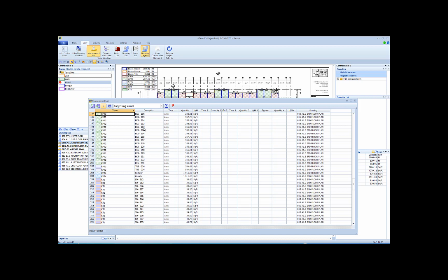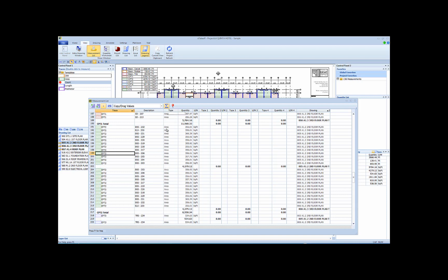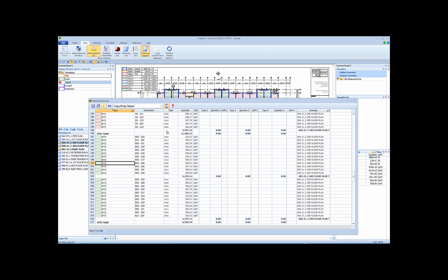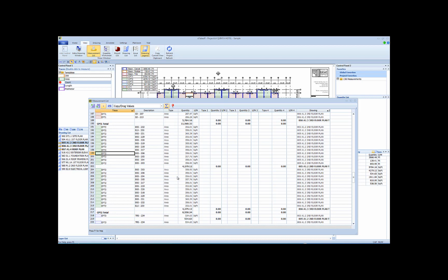You can also subsort by any other column in the list by right-clicking on the column header that you wish to subsort by. Then click Subsort By, Ascending or Descending. Once a sort sequence is defined, you can show or hide subtotals by pressing the Subtotal button in the toolbar. Subtotal rows are displayed in a bold font. This example shows a total by material with subtotals by drawings.